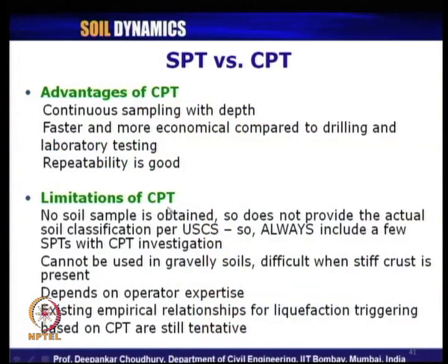So, that is why the SPT test is much more reliable till date, because of its easiness, and it is able to collect the soil sample which can be tested in the laboratory, and you can have a direct feeling, you can see the soil existing much below the ground surface, which cannot be seen so easily. So, SPT is advantageous over CPT in that term. CPT does not provide the actual soil classification as per USCS. So, always include a few SPTs with a CPT investigation, like what we mentioned for the SASW test also, you remember,